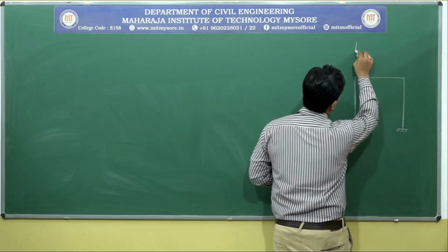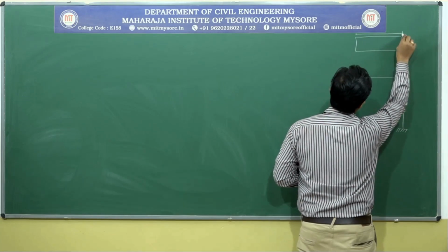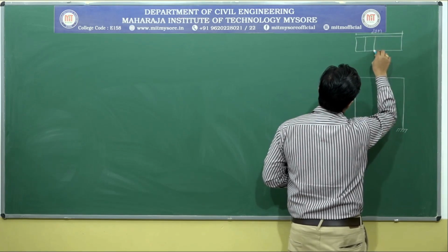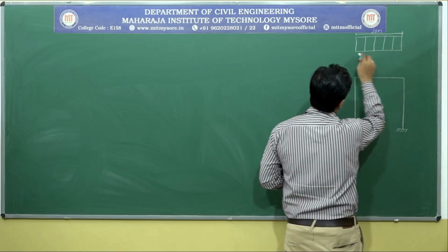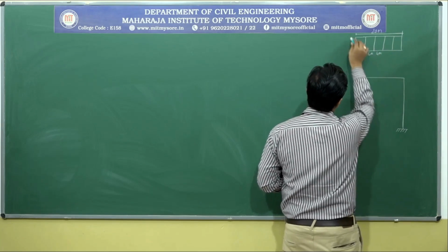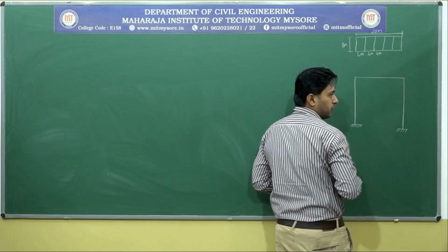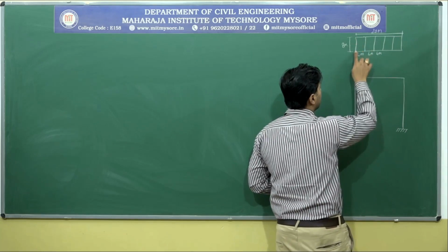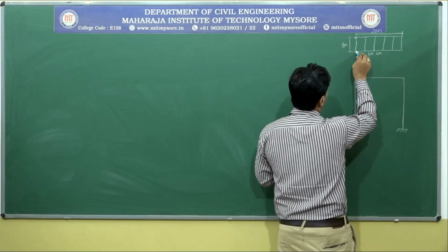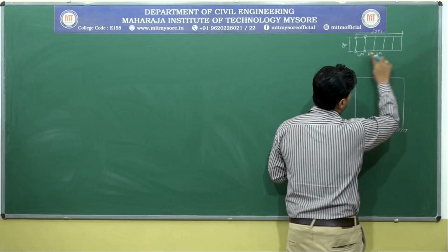I think you people remember one more thing. The total length was 20 meter. So at equal spacings, you people were having the beams like this. 4 meter, 4 meter, 4 meter, everywhere 4 meter. This particular distance was 8 meter. Now as I am concentrating on the beam, this is one portal frame. This is one more like that. We are having the columns at all these particular junctions.